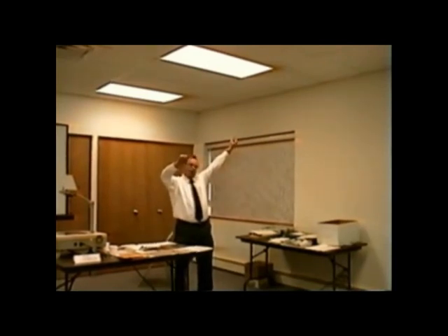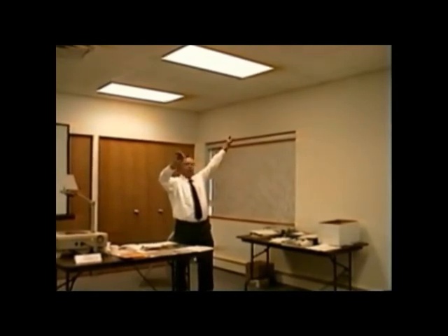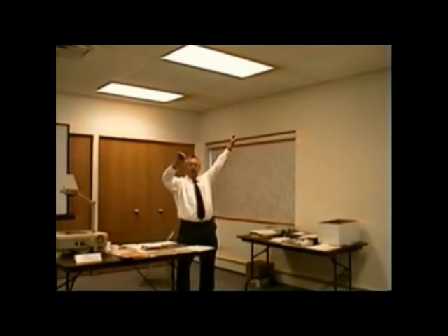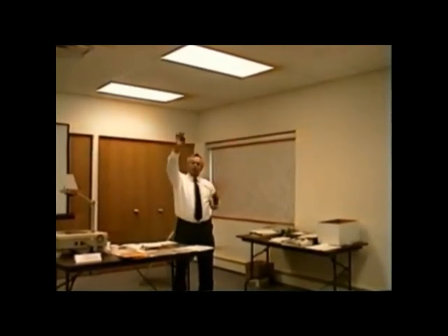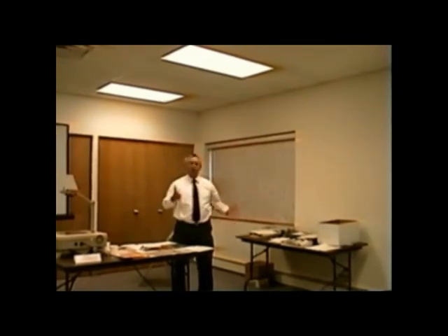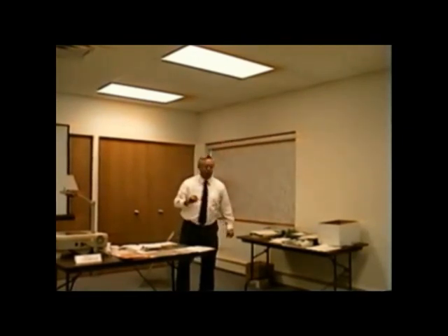Now, a lot of the books tell you not to put the thermocouple there because you get radiant heat from the heat exchanger. And I got to tell you, whenever I had a factory rep out and we would talk about this, I would put my probe down here 5 or 8 feet, and he would stick his right above the A coil, and really, the temperatures were the same. But it's up to you. All we're saying is, get a good supply temperature wherever you feel comfortable doing that.